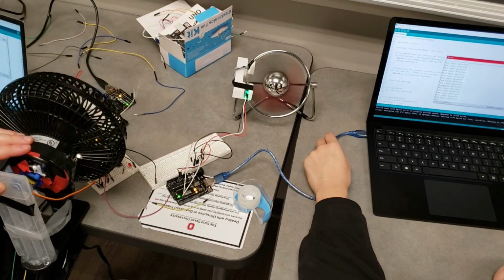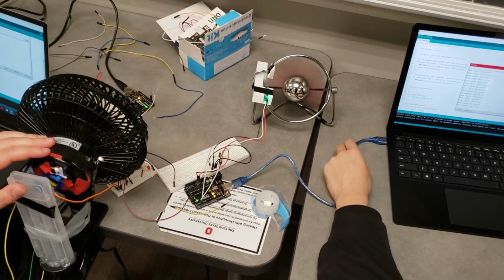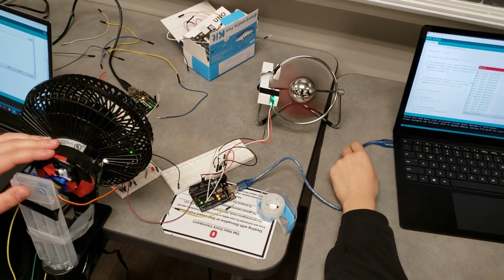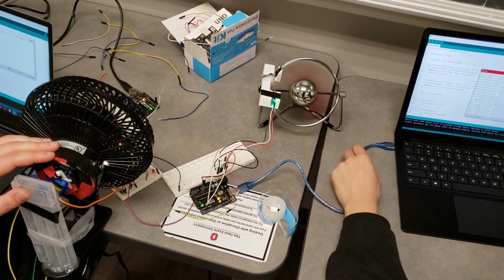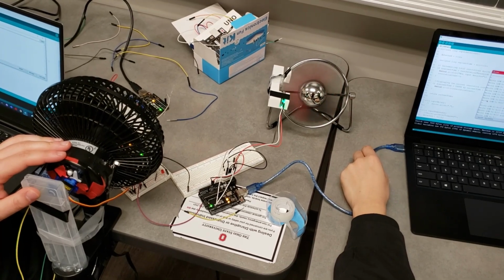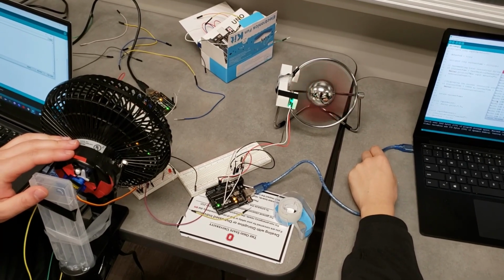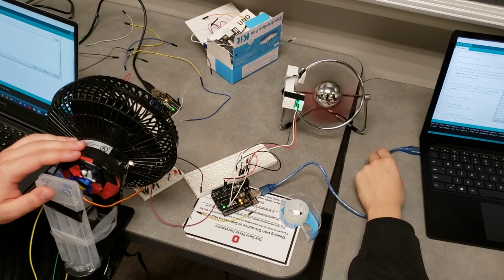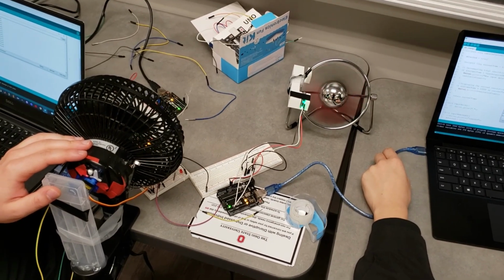We have a phototransistor taking samples that are being converted to the average RPM of the wind turbine blade over a span of 60 seconds. This tachometer is being used to measure the speed of the wind turbine blade and is used to determine when the speed breaches a high threshold level. Once this high threshold is breached, we have set a step motor to turn off our wind turbine.